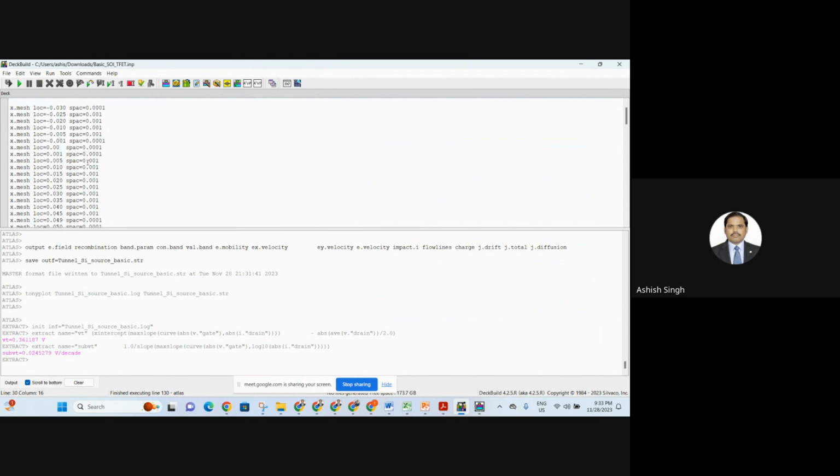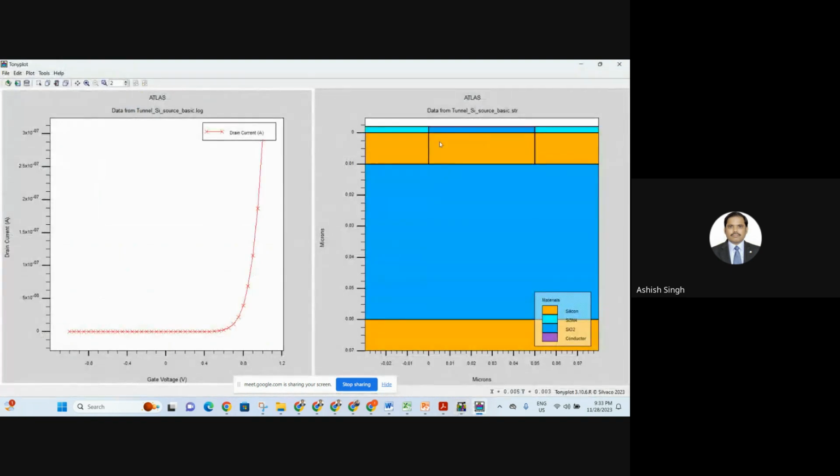And you can see somewhere 0.30 is written and somewhere 20 only. Why is it so? Where is the junction? At this junction, the source junction and drain junction, I have done very small meshing. It is dense meshing, you can say. Dense meshing, why?